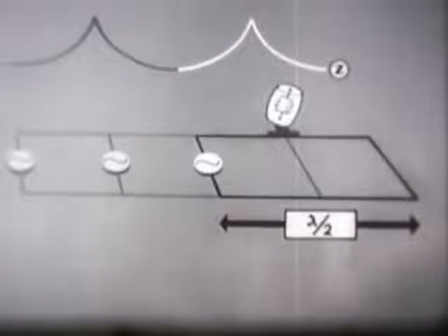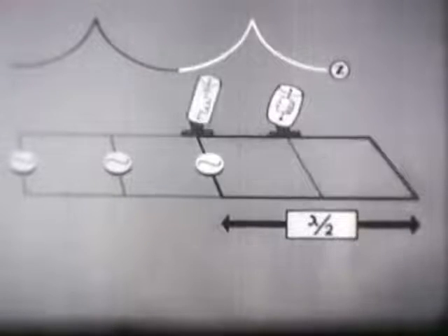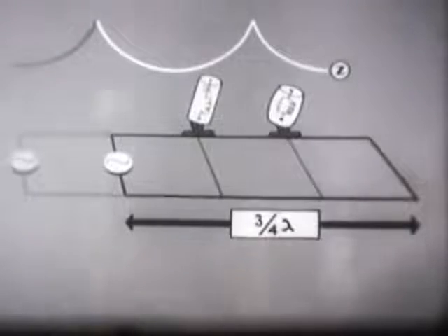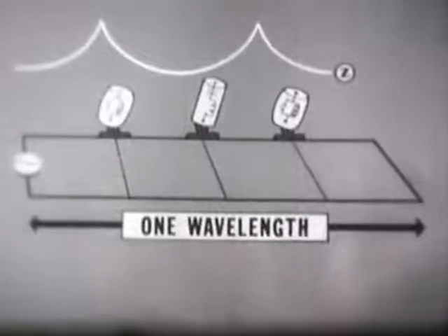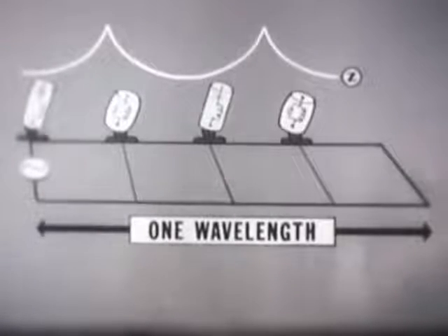Impedance is low, and where a line presents a low impedance to the generator, it is the same as if a series resonant circuit were connected to the generator. At the 3/4 wavelength mark, the impedance is again at maximum, and again the generator sees a parallel resonant circuit. At the 1 wavelength mark, the generator sees the circuit as a series resonant one.